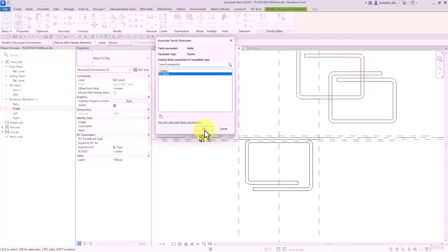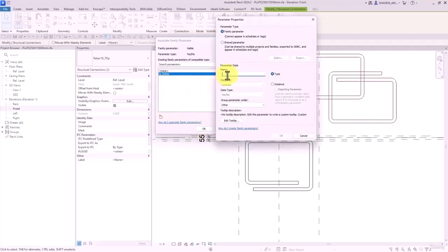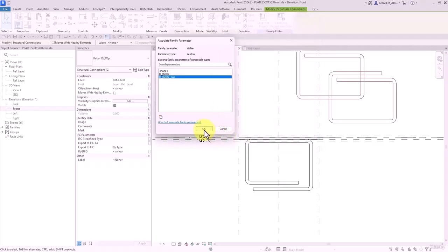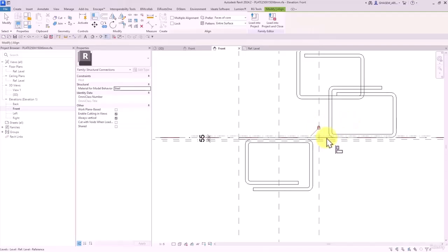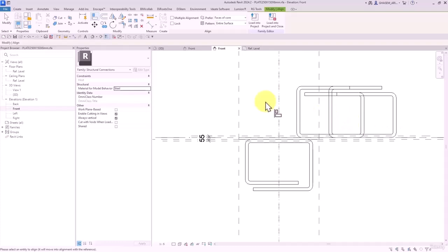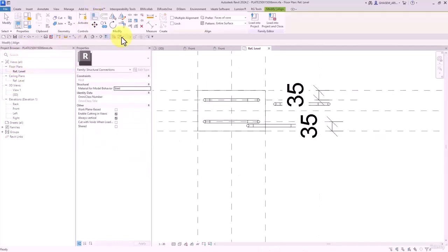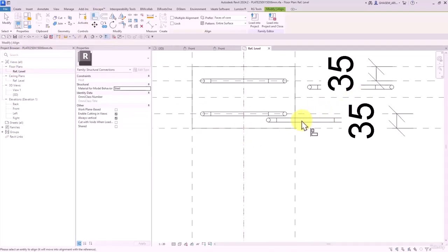consider a parameter for it, use rebar, but here I need to have two parameters. Is rebar top. Okay, align this one with here, lock, this one here, lock, middle, plan, the middle of this with here, lock, and here as well.